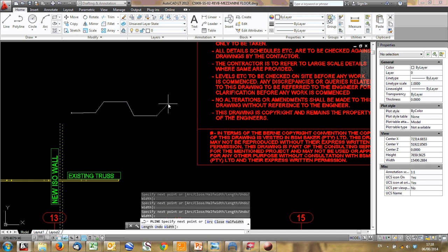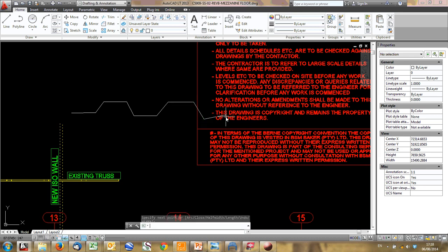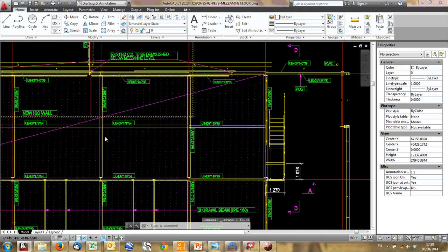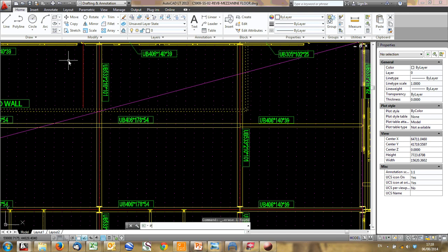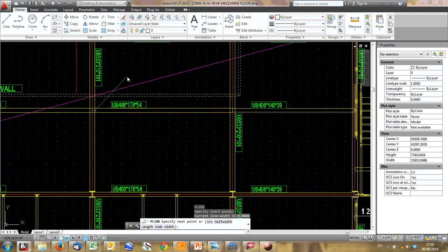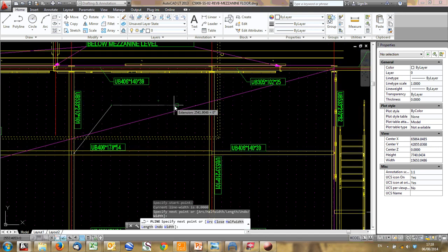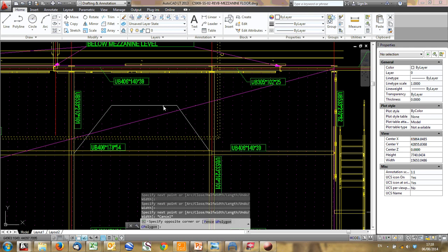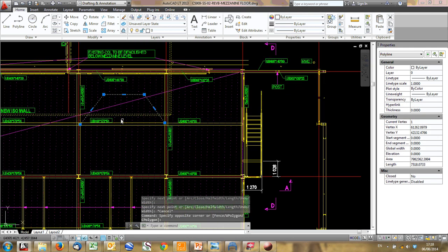The bottom profile, and then you fill up this trough. You fill up this trough with concrete. This structure was actually flat on the bottom, so it would span two ways. So you get triangular loads. So if you're going to analyze this beam, you might say the load acting on it looks something like that. And obviously you'd mirror this and you get the load on the other side, and then you can analyze it.